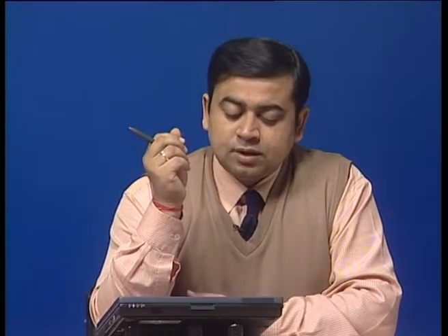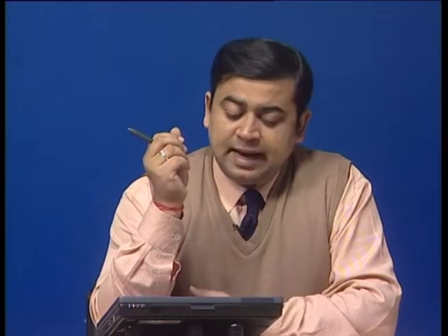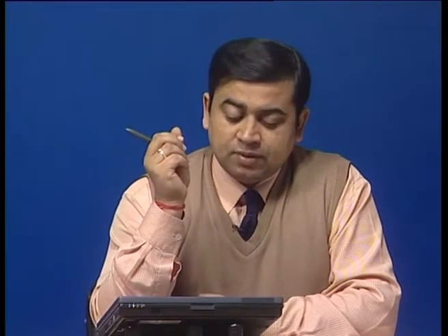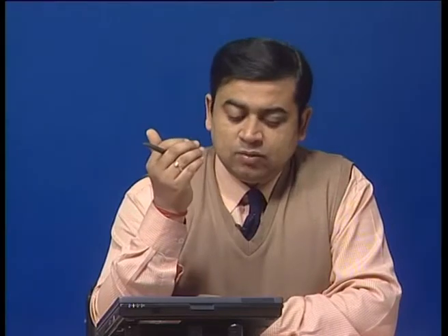So, the surface forces act on the boundaries of a medium through direct contact, which means that if we consider the fluid as a bulk flowing through a pipe, then the borderline between the pipe and the fluid is where the surface forces are directly acting, and there is an impact of these surface forces into the bulk of the fluid. And also forces developed without physical contact and distributed over the whole volume of the fluid are termed body forces. So, essentially it is a volume force that we are referring to.